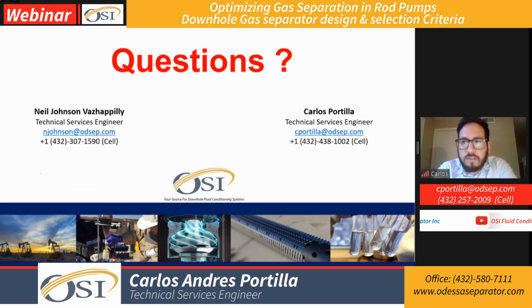So what I'm trying to say is, it is possible. We just need the PVT properties information, so we can calculate the properties at that specific point, to see how much gas the vent tool is capable of separating. Also, I will need to evaluate the pumping speed and the pump stroke length. So we can calculate that, but yes, it's absolutely possible.